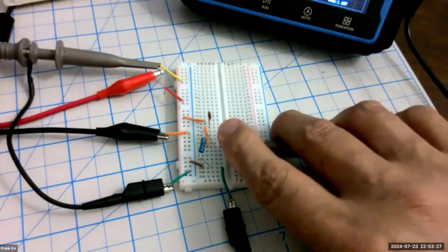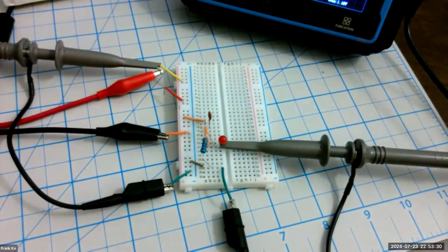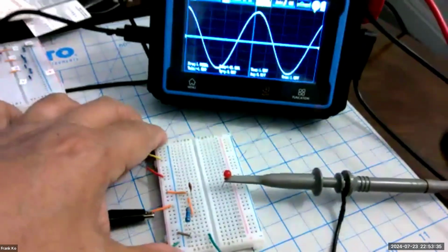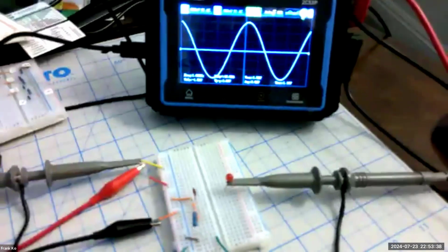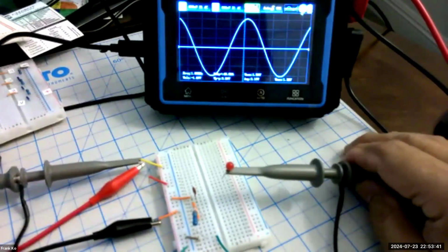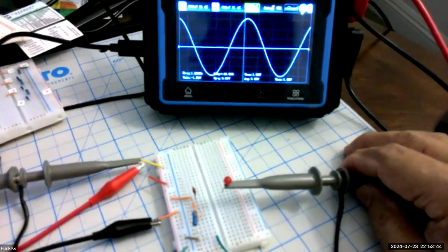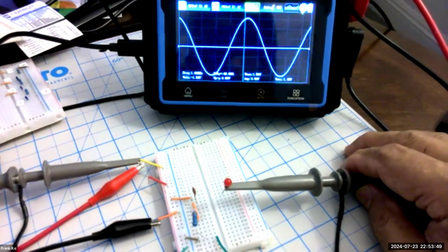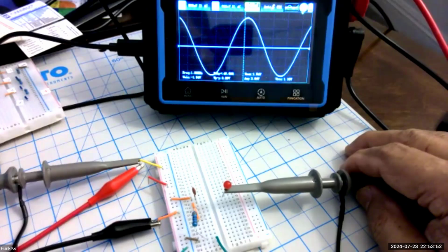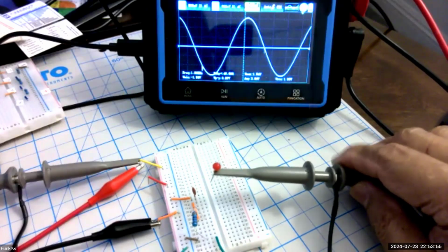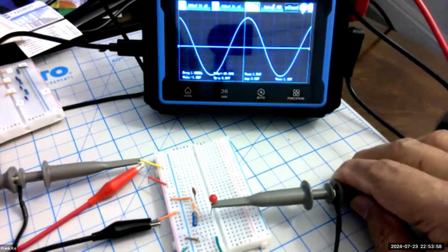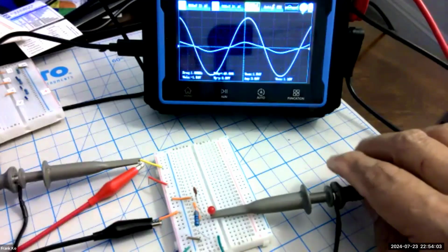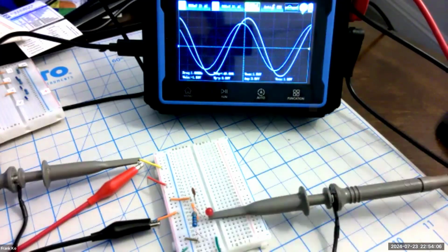If I go to connect this in here, do I see two wave shapes? I'm sorry. Let me just pull this out, show you this view. Okay, so right now my channel 2 is not connected at all. I'm only showing channel 1, which is my signal source from the tablet, and it's reading the desired frequency. Now I'm going to hook up channel 2 so that it is at the top of the resistor, which is the way we had it in our slide. Pop this in here like so, and push down.